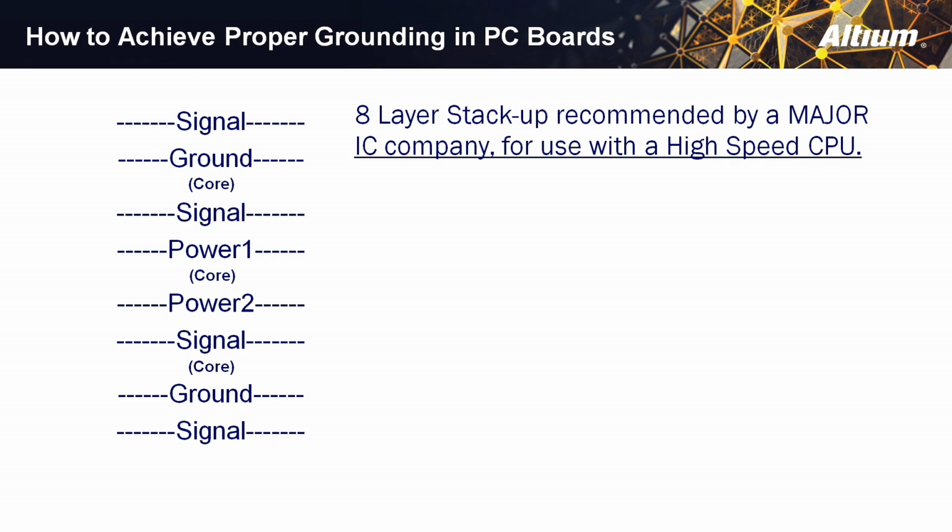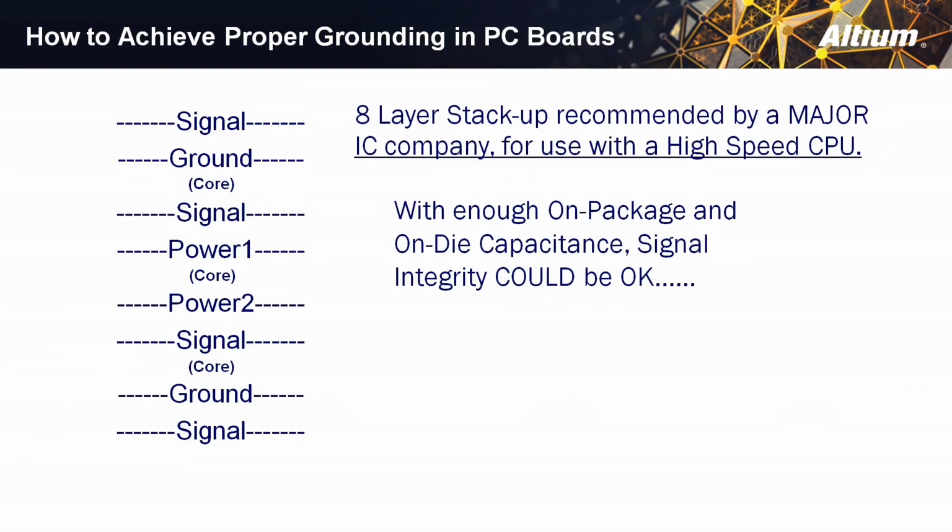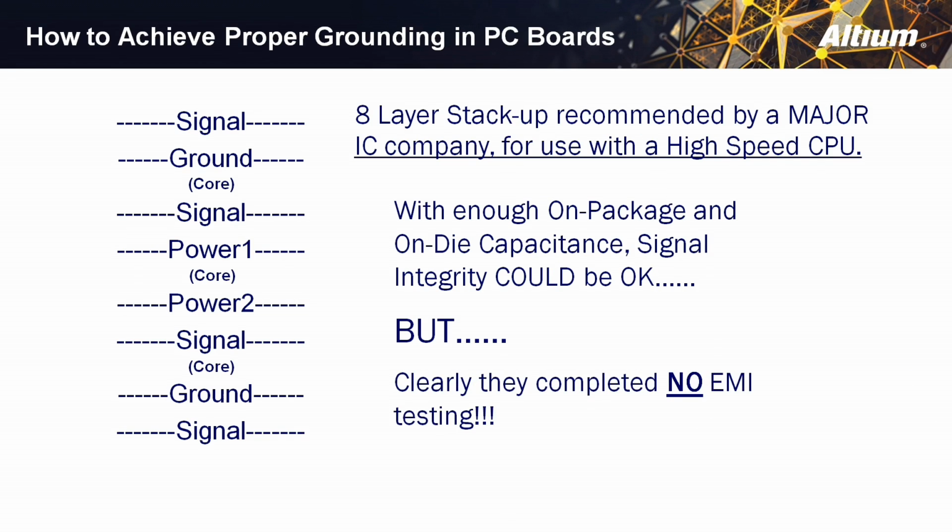This is an 8-layer board recommended by a major IC company, and I won't mention their name. When I'm doing a smaller class in a company, I will generally talk about who this is. But in their app note for this particular processor, it was a 1300 pin processor, and they said, we know that some people need low layer count boards, and this is the lowest layer count board we were able to create to make this IC work. And the truth is, I can believe that with enough on-die and on-package capacitance that they made this board work. But one thing I'm certain of, this board could not pass EMI testing.